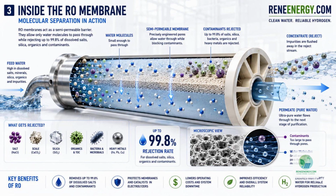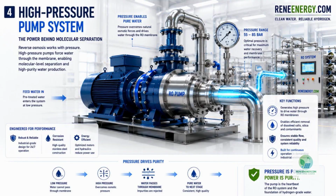In a normal screen filter, particles are blocked because they are physically too large. In reverse osmosis, separation happens at the molecular level. Pressure forces water across the membrane while dissolved contaminants remain behind. That is why RO can remove a very high percentage of dissolved salts and impurities before the water moves toward electrolyzer-grade polishing. Image 4 focuses on the high-pressure pump system.